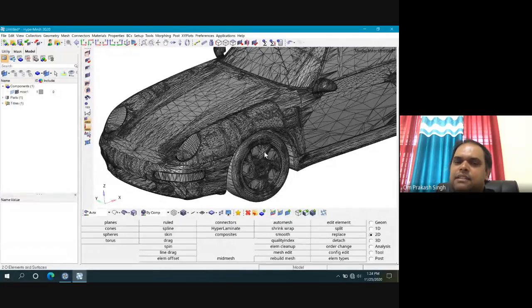You can extract the surface information from this mesh information. Okay, so this is how you can go. Start with the physical design, scan it, stitch it, get the STL. Then from the STL mesh model, you can get the surface model. So you can get the CAD model, basically the design, which any industry will never give you.